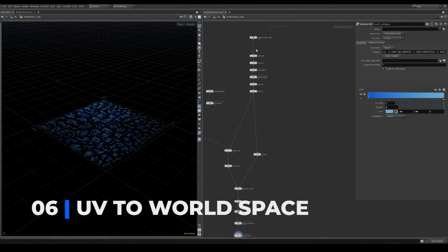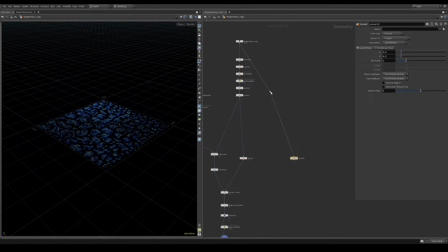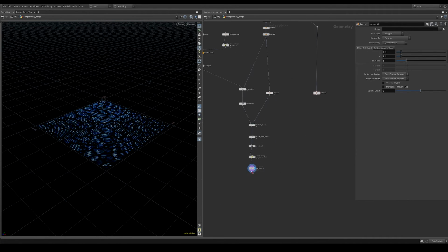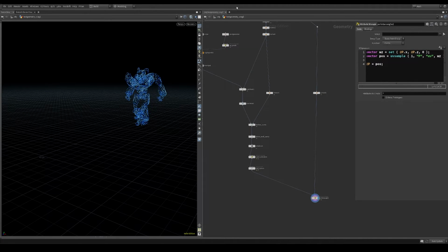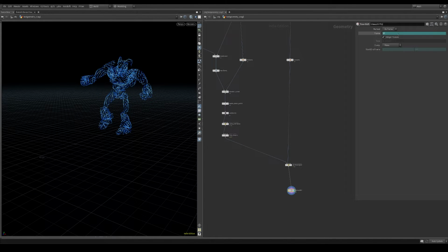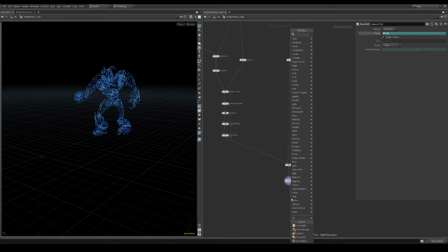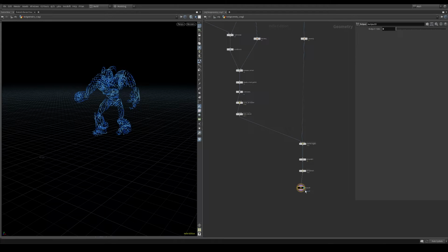Before we project the curves onto our geometry, let's go ahead and fetch the moving crag. Create a point wrangle node with the curves in the first input and the moving crag geometry in the second input. I use the UV sample function to project the curves back onto our moving geometry. I then went ahead and offset the animation a bit, and I also use a time blend node for Redshift motion blur. At the end I use an output node.